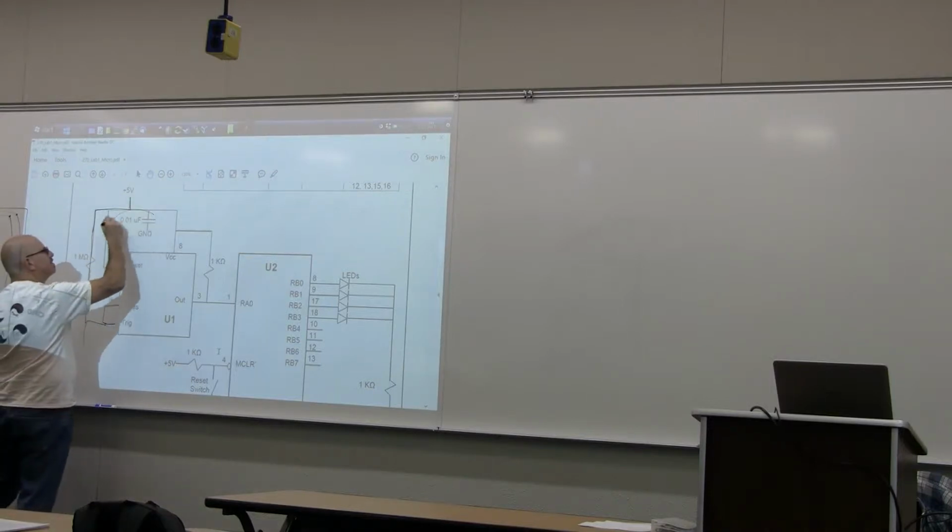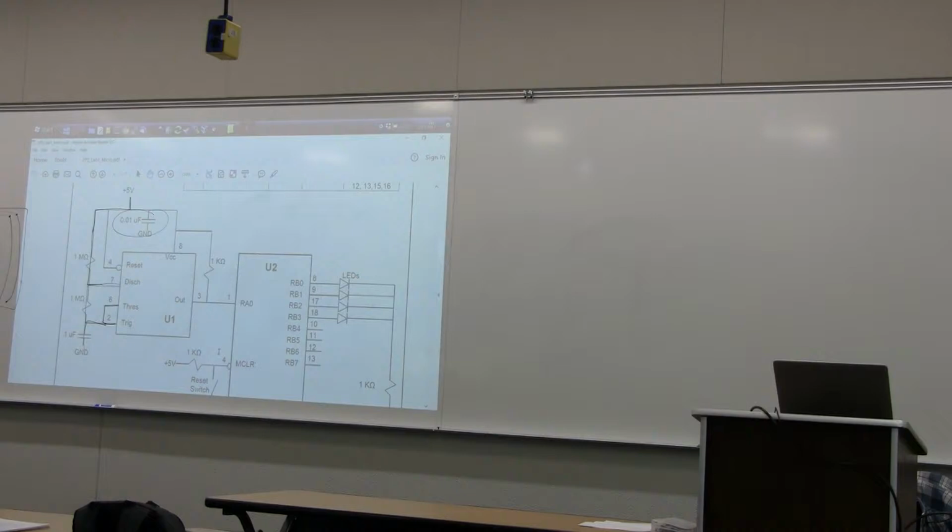All right, this capacitor is different. This is called a decoupling capacitor. It's meant to smooth out power line fluctuations. It doesn't electrically connect VCC and ground, but if VCC starts to vary, it will smooth out those fluctuations. For this lab, you can really just take your little 1 microfarad, plug one end into ground, one end into power, but do it physically close to the chip. The closer it is to the chip, the better it will work. We'll come back and talk about this in a lot more detail when we start working with motors. But for now, just throw it in somewhere between power and ground. That takes care of this.